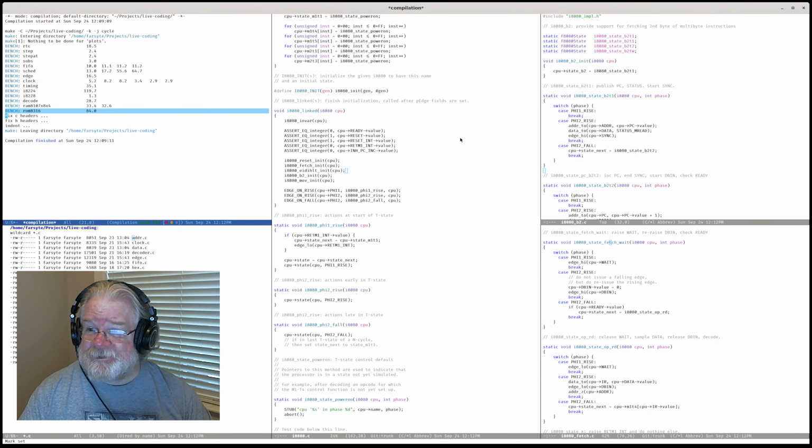The only way we can eliminate the storage items that support hazard detection is also to eliminate the Z state. So as part of turning that off, we would then lose the ability to have an explicit Z state. But that means that all of the places where we test the Z state in our test code have to be, oh, and maybe we have a function that says I might be Z and a function that says I might not be Z, which can return, I don't know, or the tests have to say, well, if we're compiling in fast mode, then we don't test this because we do not have a defined Z state. Okay.